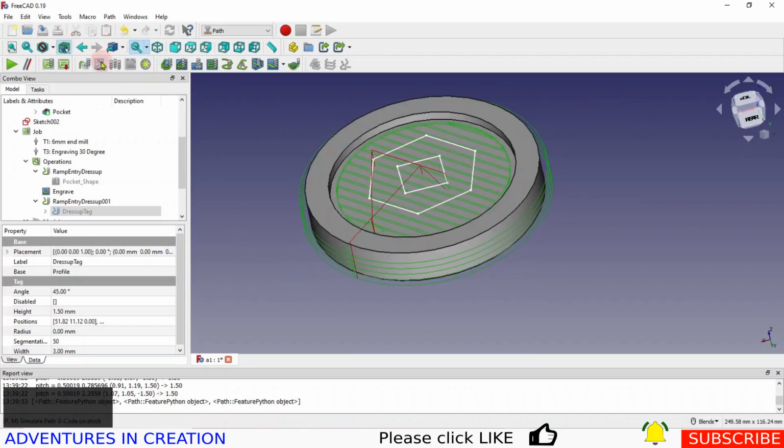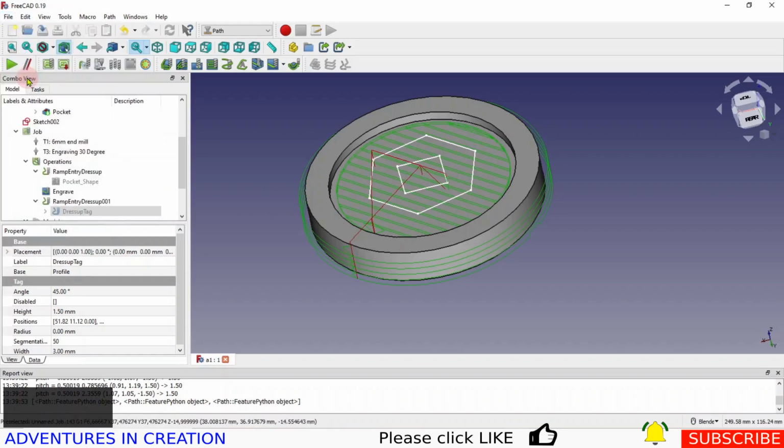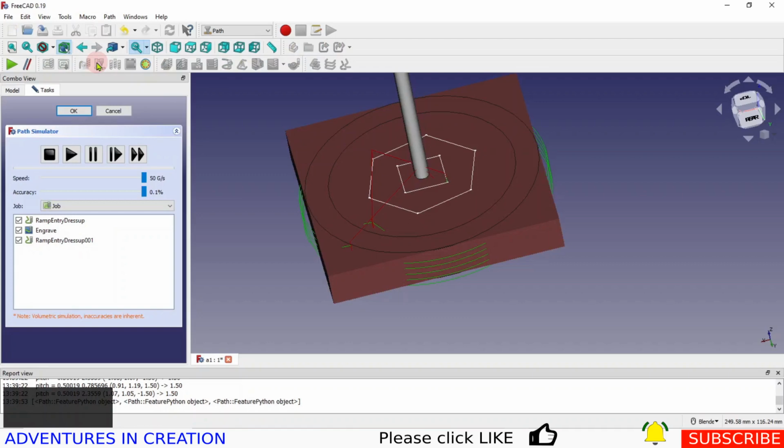We can do a simulation. I'm just going to do a save before I do that because I think it's a smart move. And we're going to do a simulation. So with the simulation, I can do the whole thing. I'm going to take that one off because it takes a long time. I can do just the engraving. So if I click OK, or start, sorry, you'll see the engraving.